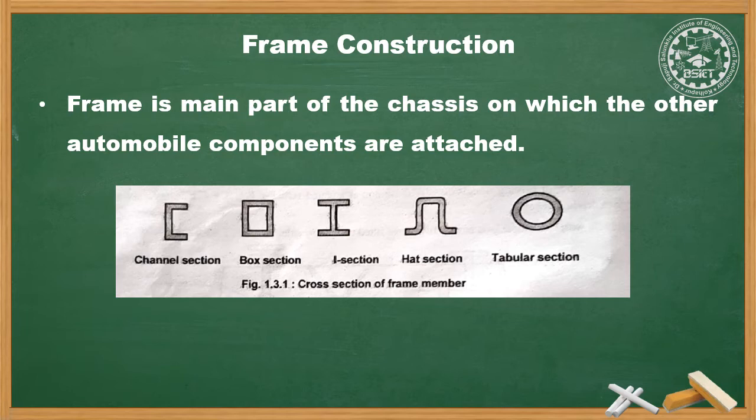The tubular or box section cross members provide support to the body and increase the torsional rigidity of the frame. They also provide brackets for mounting the spring. The construction of frame with box shaped tubular or steel members welded together is known as ladder frame arrangement.